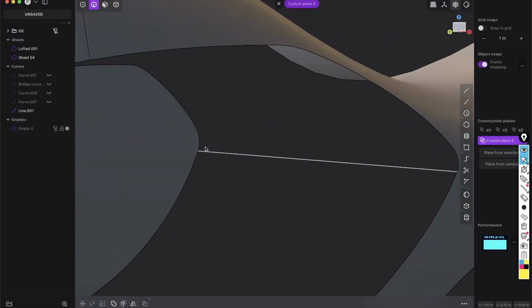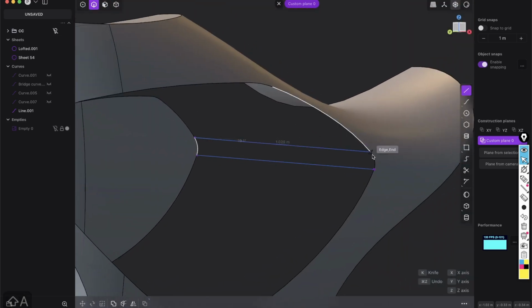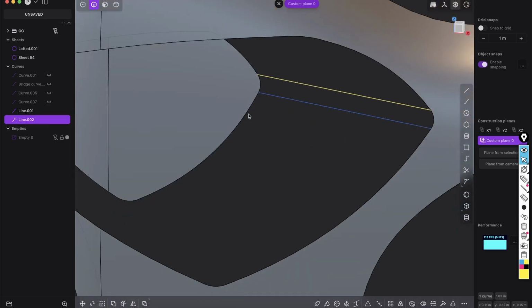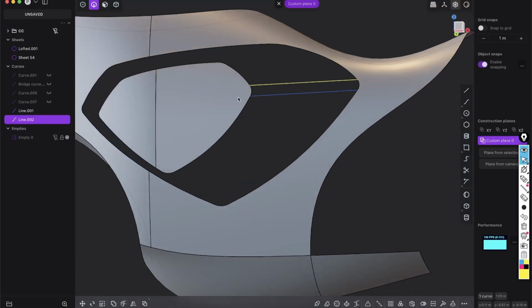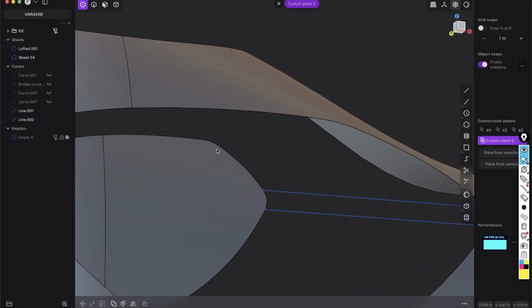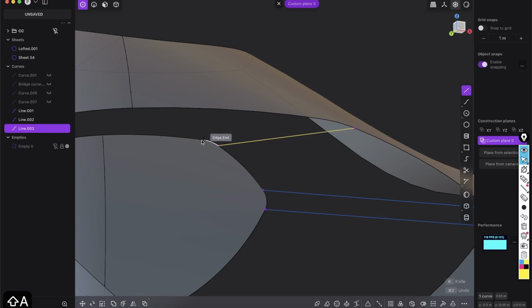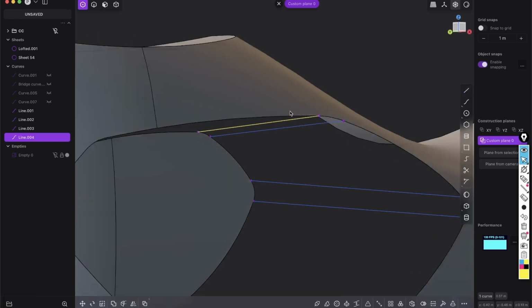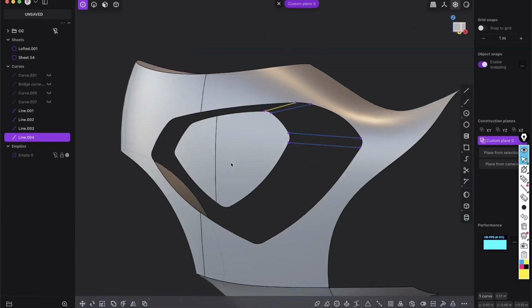But let's continue here. So again, just create Shift-A and go to this point. And again, it's just a quick tutorial, so it might not be perfect. So sometimes you have to bring in the curve to somewhere here and create those lofts a little bit differently, so you get a nice shape. But let's just see what we will get and make some small adjustments. So again, I will first of all connect those points here with each other with the Shift-A line, and then let's see what we will get.